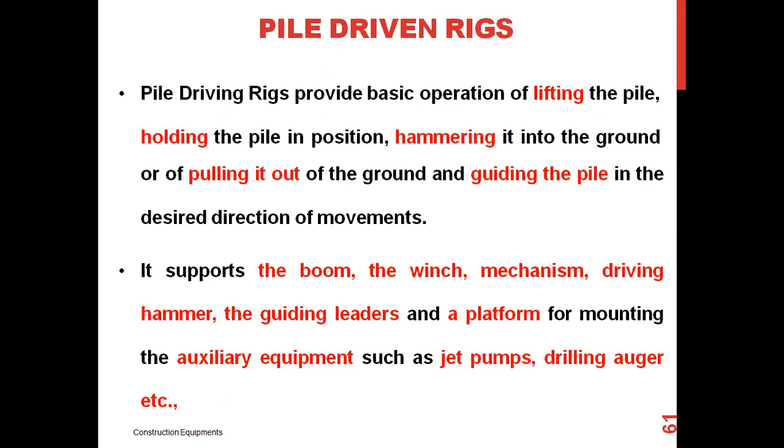So pile driving rigs. How do these driving rigs provide the basic operation of lifting the pile, holding the pile in position, and hammering into the ground or pulling it out? These pile driving rigs provide the basic and essential operations for the pile which has to be lifted or fitted into that hole, held in its position, or hammered into the ground. Here these rigs help to provide guiding of the pile in the desired direction of movement. They also support the boom, the winch and mechanism to drive the hammer, the guiding leaders and the platform for mounting the auxiliary equipment such as jet pumps, drilling, auger, etc.